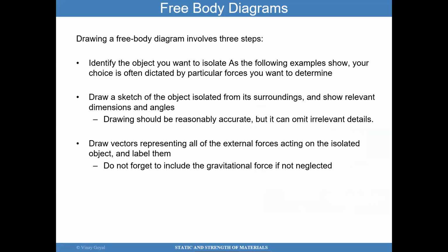So drawing a free body diagram, what does it involve? You want to identify the object you want to isolate, and the choice is typically dictated by the particular forces you want to determine. You want to be smart about how you isolate it. You don't have to isolate everything. It depends on what you're trying to solve.